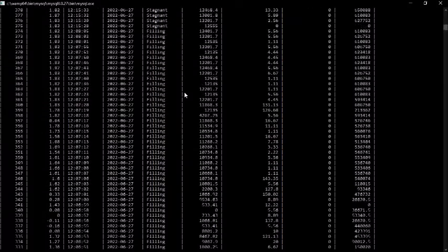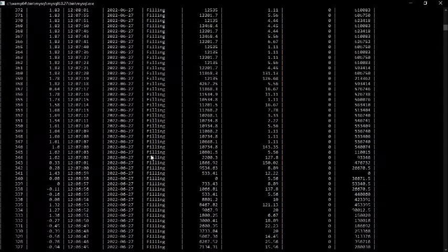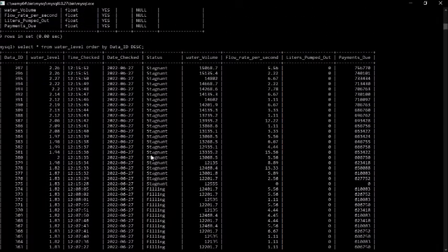And as I said, the negatives are because of sudden changes in the distance between the ultrasonic sensor and the cardboard that we were using. So anything that happens faster than the 1 second period causes a very big difference in the readings.